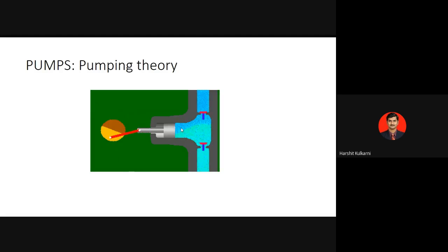So what is happening here in a pump, the design is like you will be having two valves, inlet and outlet. If you see the yellow part and this brown part, for half of the revolution, the piston will be moving from, let us take this as LHS and this as RHS, from RHS to LHS.